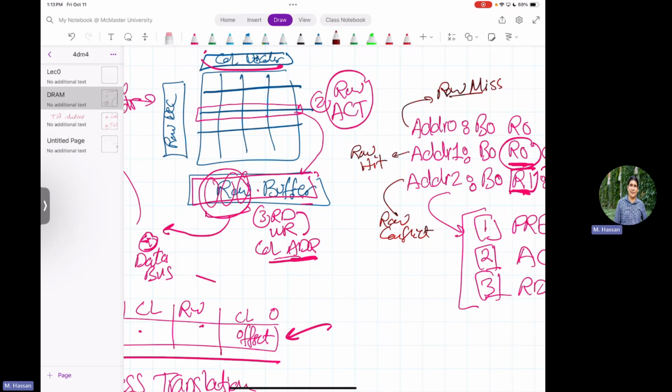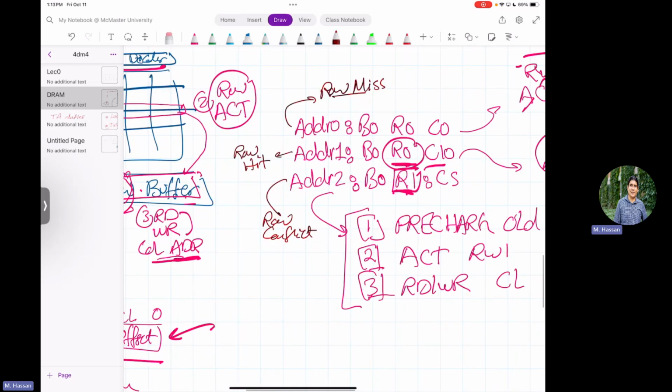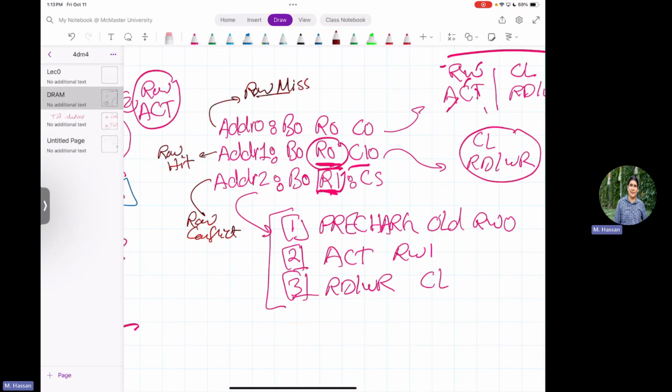Yeah, in reality, presenting the row buffer as a cache is in fact an architecture abstraction. But I will ignore the physics of the row buffer at the moment. I will come back to it later. Let's think of it from an architecture perspective. If you have your row data in the row buffer, you leverage the hits into it. And with the locality concept, any accesses that hit into the row buffer will have better latency. Well, if you assume locality, then it should be very common, right? And in addition to the locality, the memory controller also invests a lot of circuitry to do scheduling to maximize the row hits. But regardless of locality or not, you still need the row buffer.